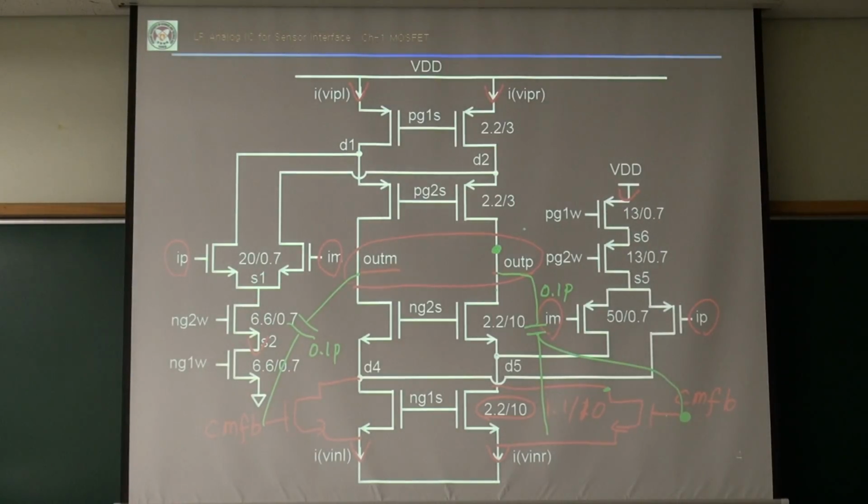You know, this output resistance looking here, R1. Because of cascode structure, this R1 is GM RO times this thing, and RO parallel, this RO parallel that RO. This RO, that RO in parallel combination times the GM RO of this transistor. And parallel with this one, there is a similar RO there, right?